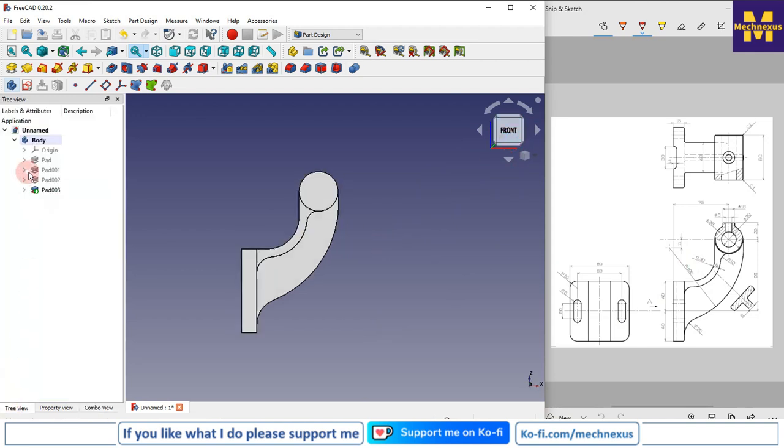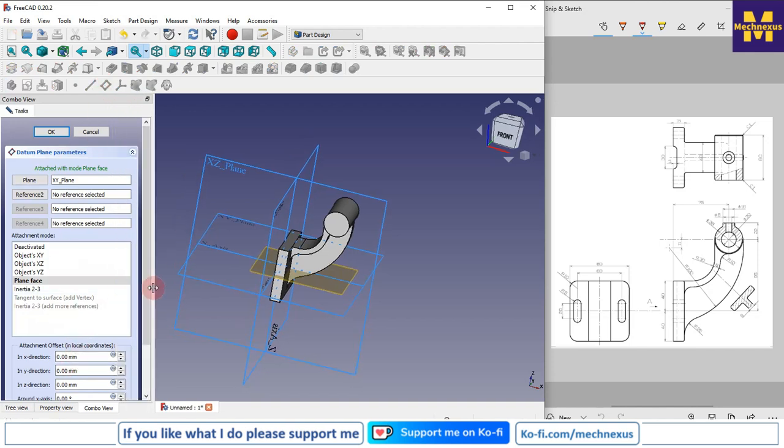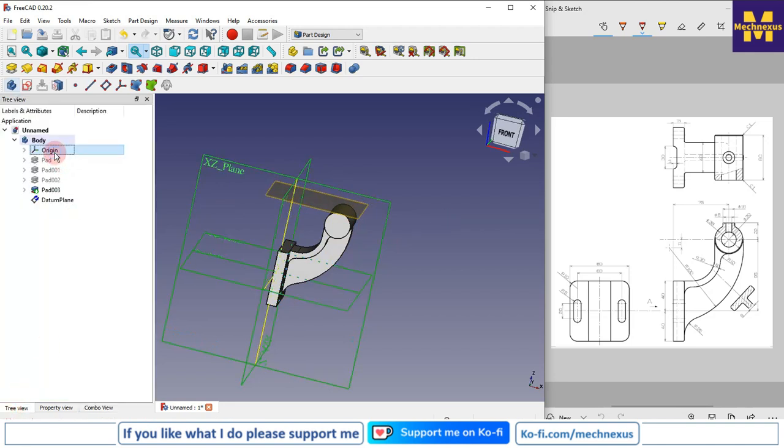So now we will again turn on our origin plane. Now if we see from our plane XY we will create a datum plane. So click on the datum plane and in the Z direction I will add the dimension, which is 95 plus 22. So here I will give 95 plus 22. So you can see that a datum plane has been inserted. So I will click on OK and I will turn off my origin plane.